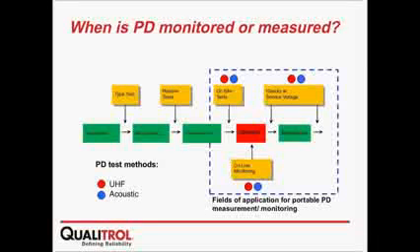During continuous operation, customers can choose to have continuous online monitoring. The preferred method there is UHF. As Carlos explained earlier, UHF is sensitive across all types of partial discharge events within a GIS or a transformer. So that's one reason. The other reason, as I explained earlier, is that the number of sensors required for the UHF method is substantially less due to the sensitivity and the range. So the cost of online monitoring is substantially less using the UHF method.